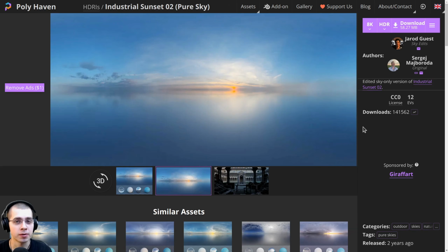Now I am going to be using a few different free resources online to make this tutorial, so all the links will be in the description if you'd like to download them. So here on Polyhaven, I'm going to be downloading this Industrial Sunset 02 Pure Sky, and because we're going to be seeing this in the background in our final animation, I'm going to be downloading the 8K version, so it is higher quality. And I'll just download the HDR version.